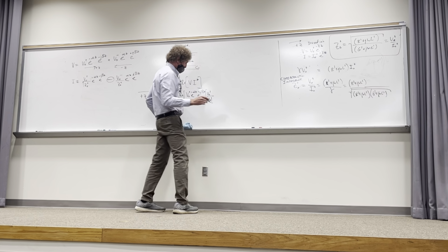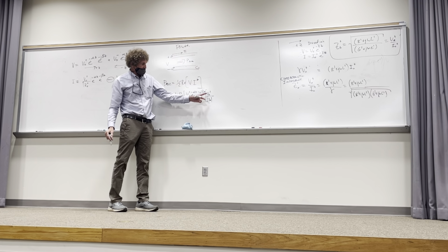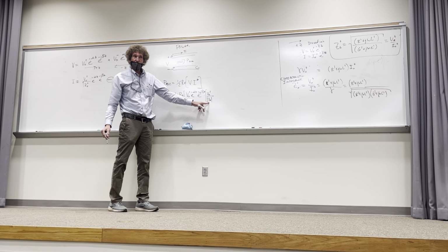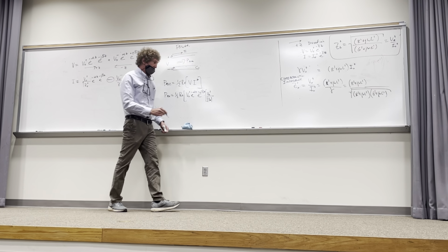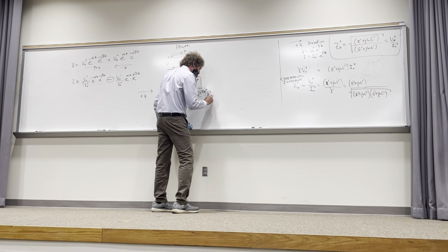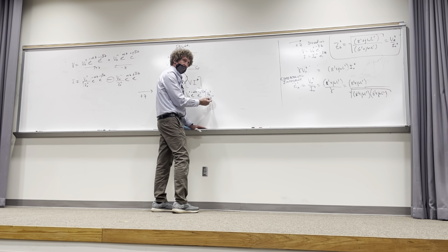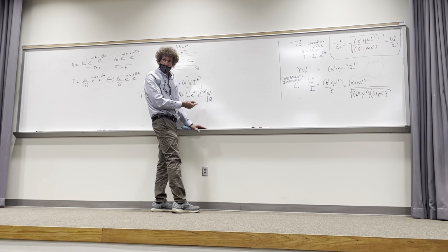Let me explain this. Remember how it was V0 over Z0 plus before, class? Right, Z0 is a complex number, possibly. That means it has a magnitude Z0 plus, and it's got a phase angle. The phase angle can be written down here as e to the positive j phase angle associated with Z. Can you all follow me?